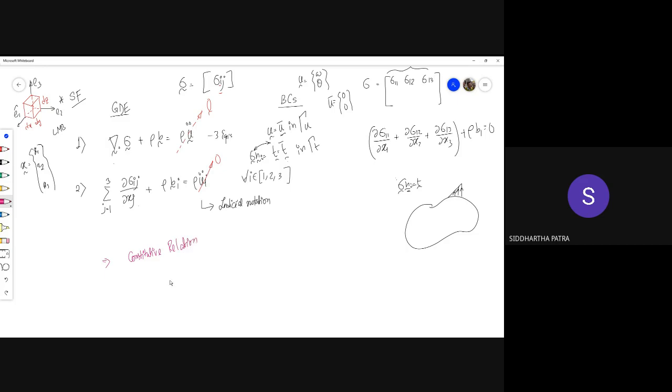Basically, on one side of the constitutive relation is the stress tensor, the other side is strain, and the functional relationship between the two is the constitutive relation. The simplest that we have seen so far is this one for uniaxial problems. In the uniaxial heat transfer problem, we have seen that the heat flux Q is K times dT/dx.